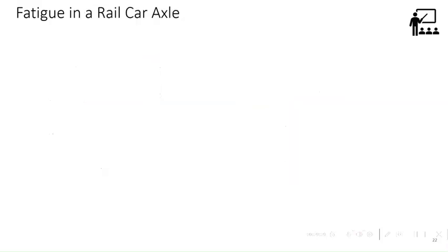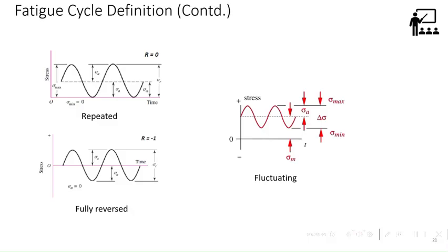In the top left graph there, can we assume that it's all positive tensile loading and no compression? Yeah, R equal to 0 means, you define R as minimum stress by maximum stress, right? Minimum stress 0, so 0 by S max. So this is a structure which is only in tensile loading.